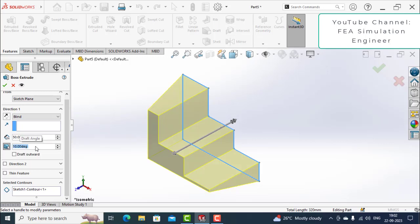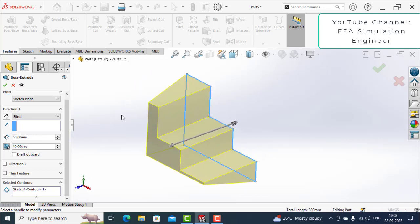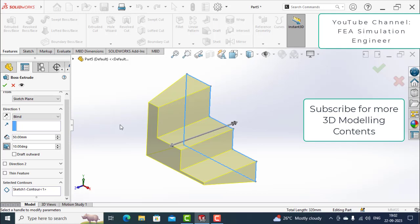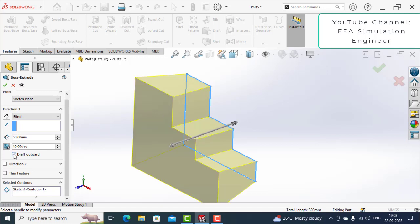I am changing the draft angle. Now you can clearly see that there is some draft. If you want to make it an outward draft, select the box. Automatically the inward draft will change to outward draft.